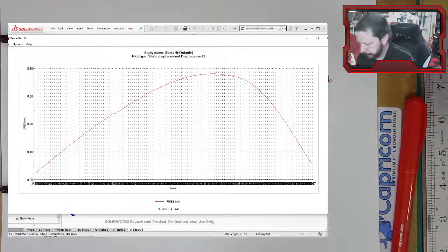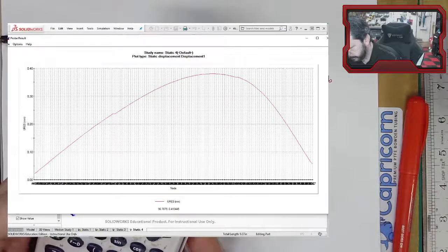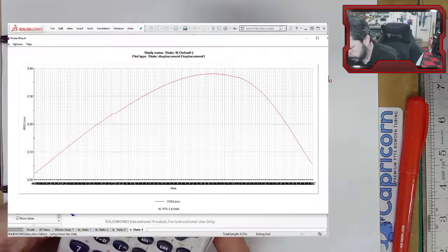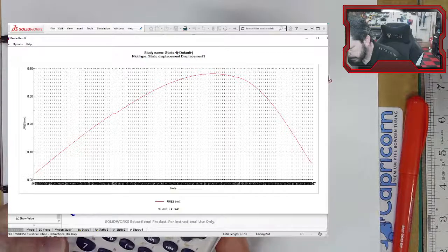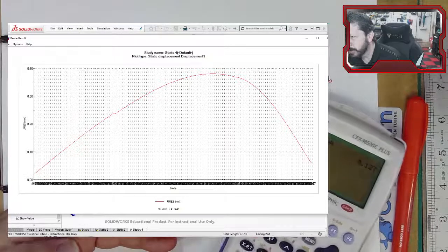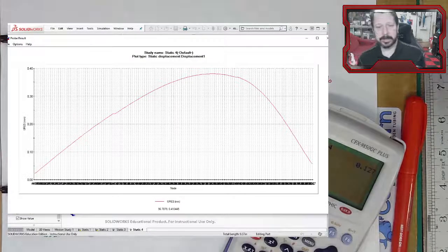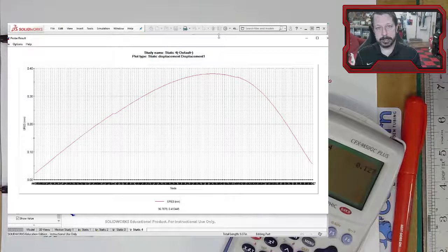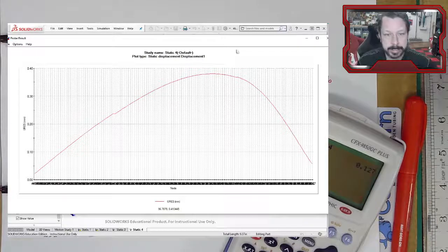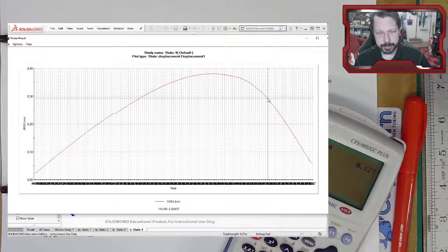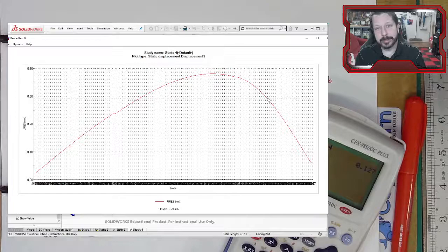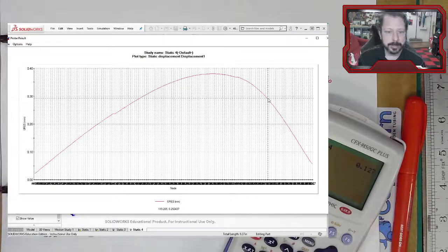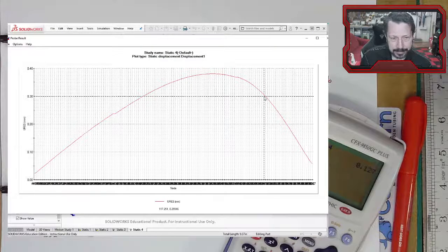Here it is. All right. 0.05 inches times 25.4 millimeters per inch. That's, I can only have 0.127 millimeters of deflection before this gear is going to be too far away from the mating gear. And this is only one gear moving. The other gear is moving also, right, on its shaft. So I've got 0.3 millimeters.